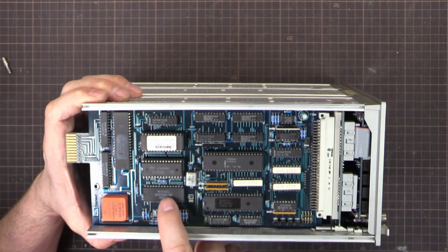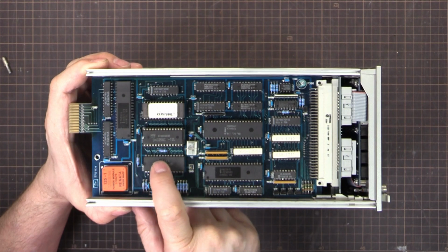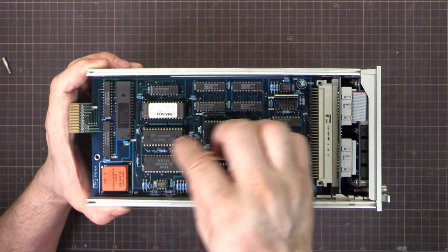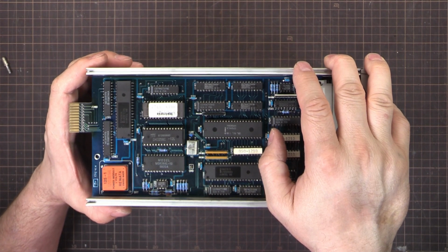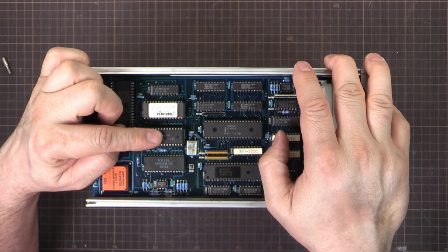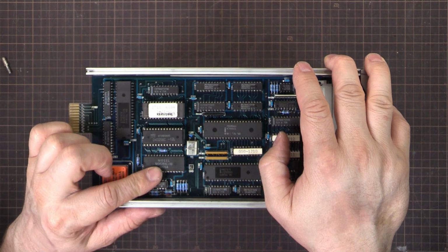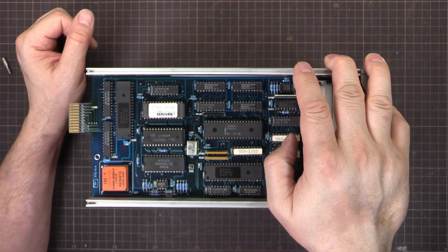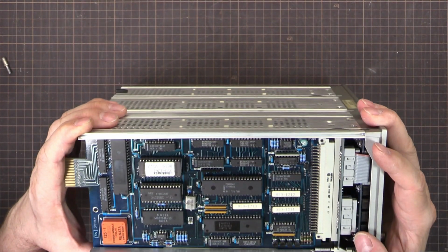This is dash 12, this is dash 10. So this is a small amount of RAM, but faster RAM. So rather than putting in a large amount of fast RAM, which is much more expensive and blowing out their design budget, it looks like they went for some slower RAM, a big lot of it, and then a small amount of fast RAM just for that arbitrary function generator function. So yeah, I believe that's what they've done there.